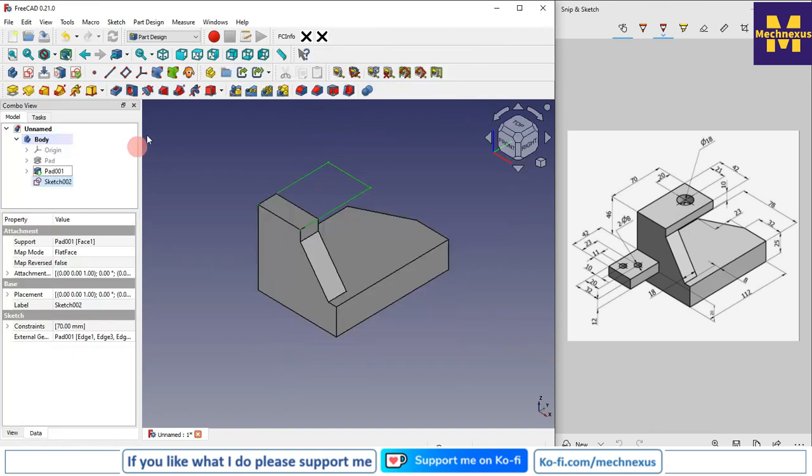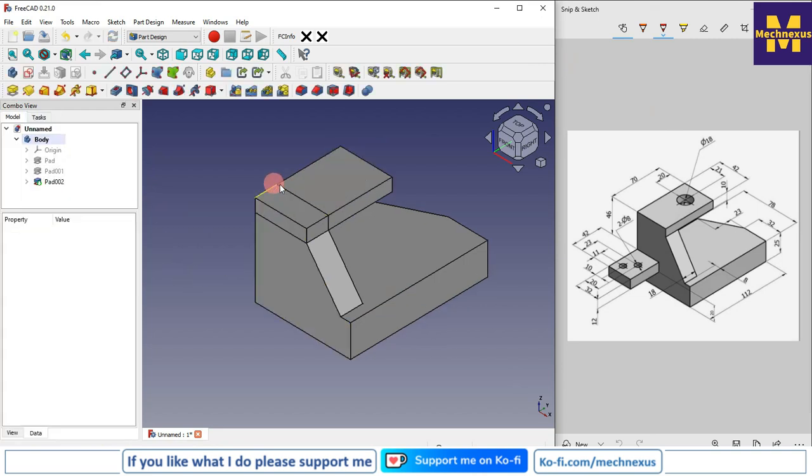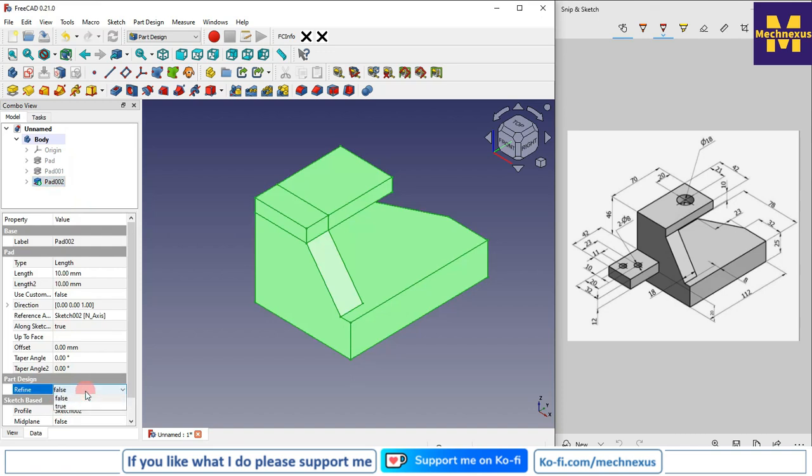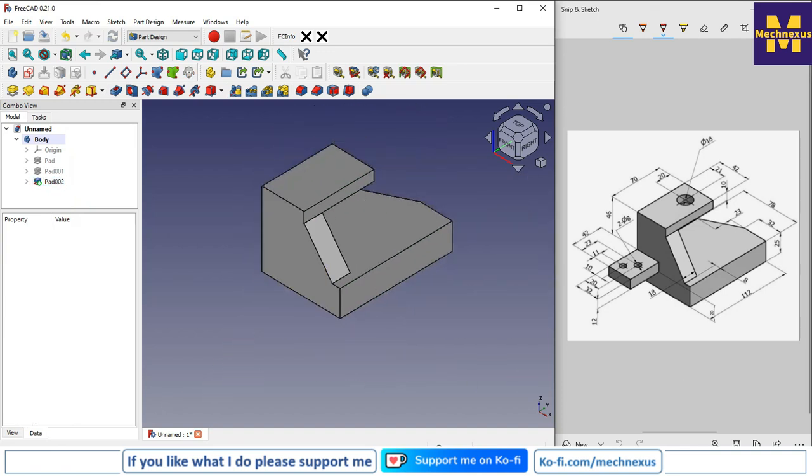Click on close, click on the pad, click on the reverse and give the 10 mm, click on OK. But you are seeing here the line, so for this again use the refine true, and now we will create this pad.